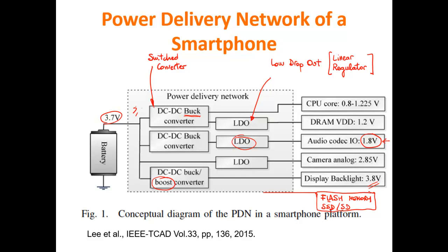The radio is extremely sensitive to disturbance and noise, and they typically need a very low-disturbance and separated power management circuit for all the radios, which means for the cellular radio, for the Wi-Fi, for the Bluetooth. They are all independently supplied with another specialized power management IC, which is anyway connected to the same battery.